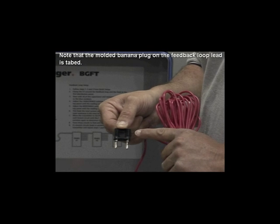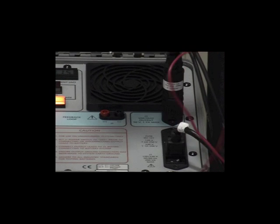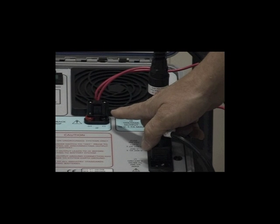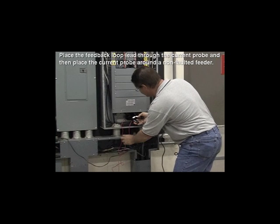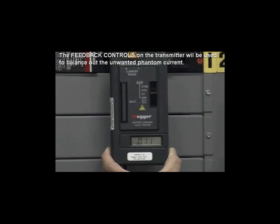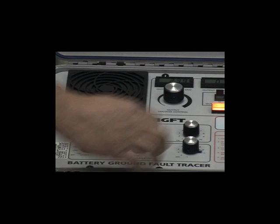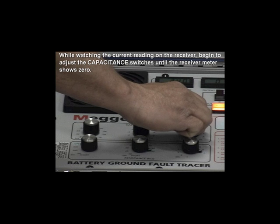Note that the molded banana plug on the feedback loop lead is tabbed. The tab plug inserts into the negative input of J2. Place the feedback loop lead through the current probe and then place the current probe around a non-faulted feeder. The feedback control on the transmitter will be used to balance out the unwanted phantom current. While watching the current reading on the receiver, begin to adjust the capacitance switches until the receiver meter shows 0.